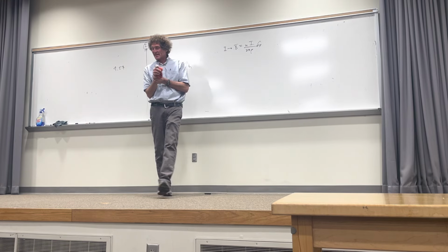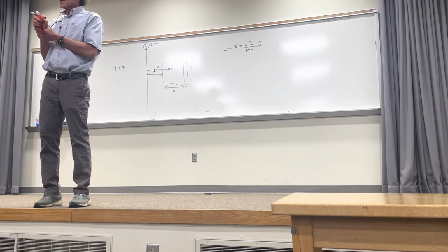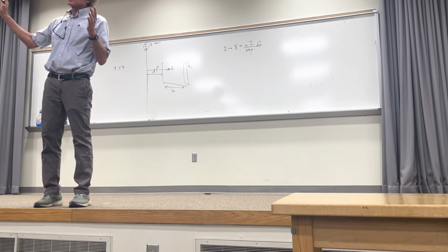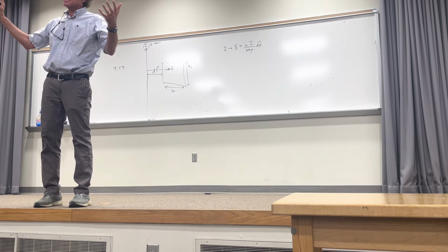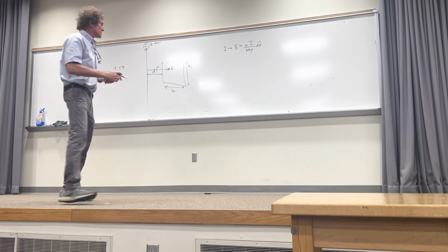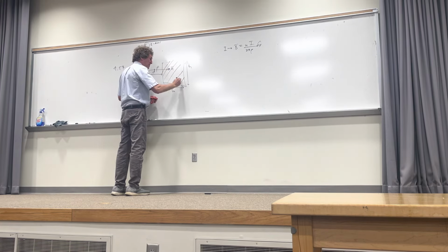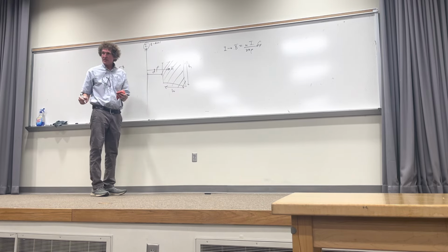Now, after that, what's the next thing I need? Think about what inductance always is. The mutual flux that penetrates a secondary circuit caused by a primary current, right? You all see that this is the actual area. I need the integral of B dot ds over right there, class.